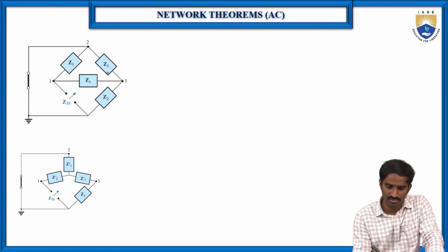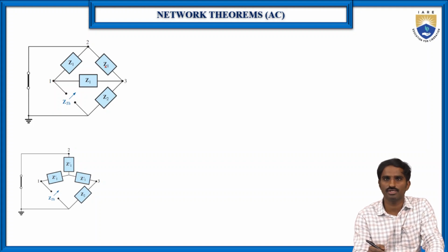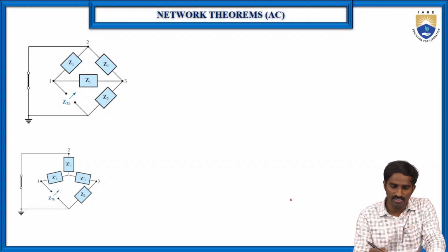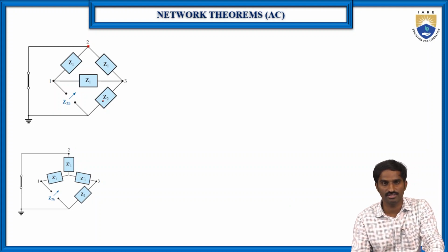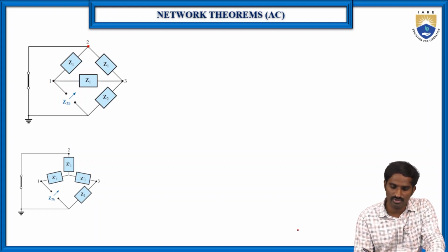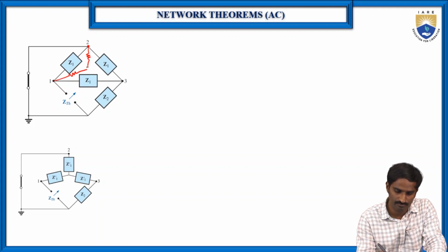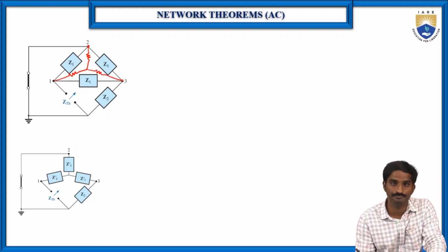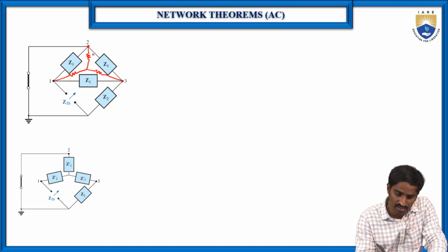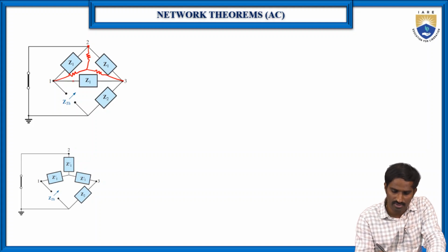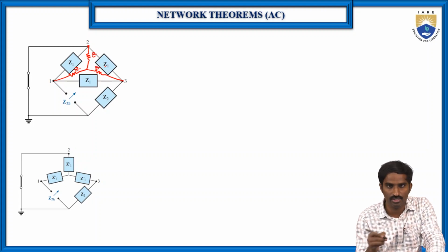So anyway, here it is impossible to identify which two resistors are connected in series or which two are connected in parallel, because of course these two resistors have one common point, but this common point is shared with the resistor Z2 again. Okay, so that's why what we are going to do here is convert this delta into the star, like this. Right, so let me consider here, because all the resistors have the same value, you will get the same values in the star also.